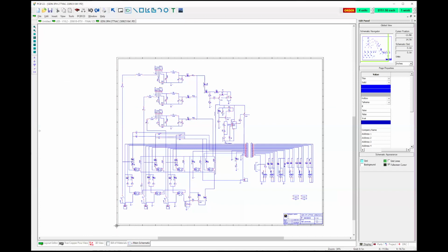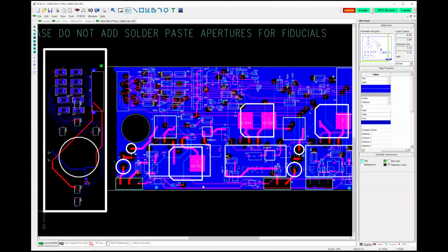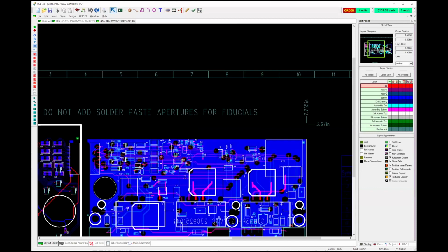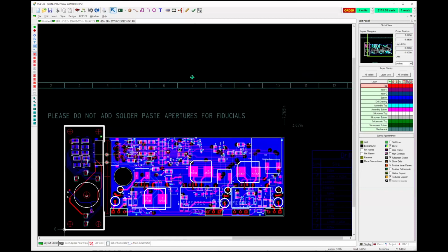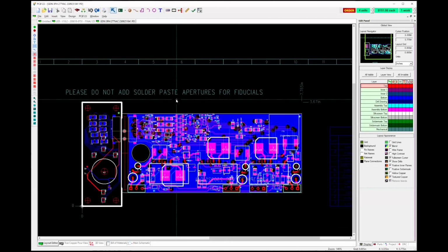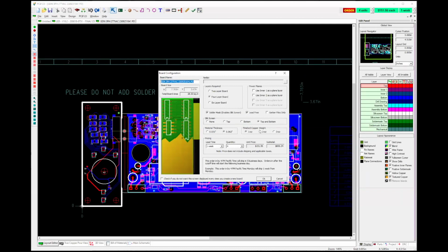Here's one, Bob. Can copper thickness be defined individually for each board layer? No. That takes a phone call. And I'm pretty sure Sunstone doesn't offer that as a standard service. The options that you have are 1 ounce, 2 ounce, or 3 ounce. And the material thickness, the options you have are 31 thousandths and 62 thousandths for this particular 4-layer board.